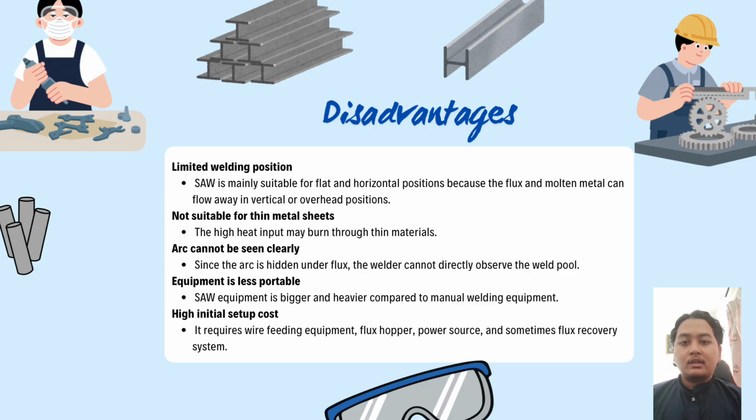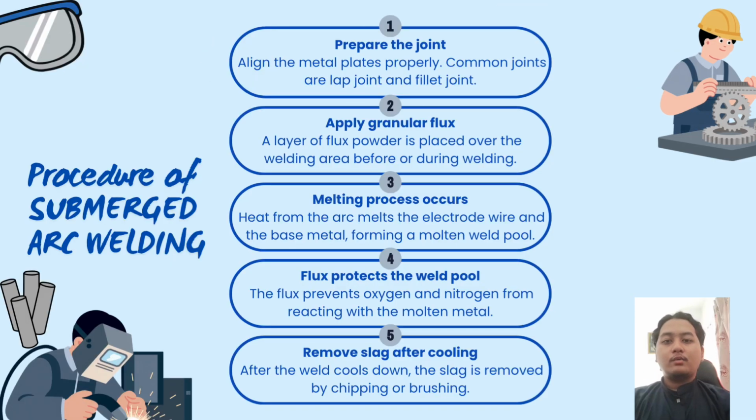And lastly, submerged arc welding has a high initial setup cost because it requires automatic feeding equipment and flux handling system. Because of these limitations, submerged arc welding is more suitable for large, thick, and continuous welding jobs. Alright, we will continue for the procedure of submerged arc welding.